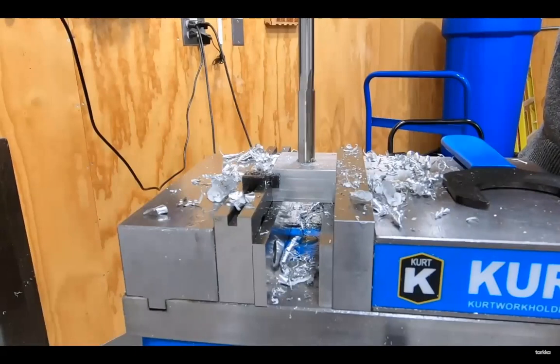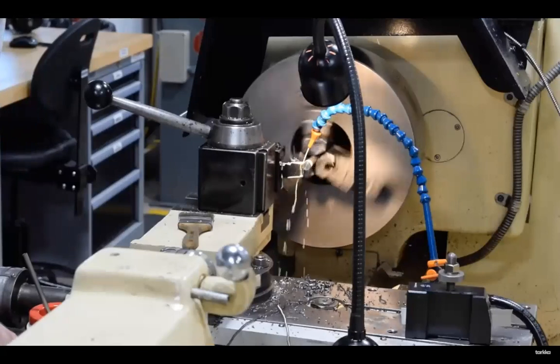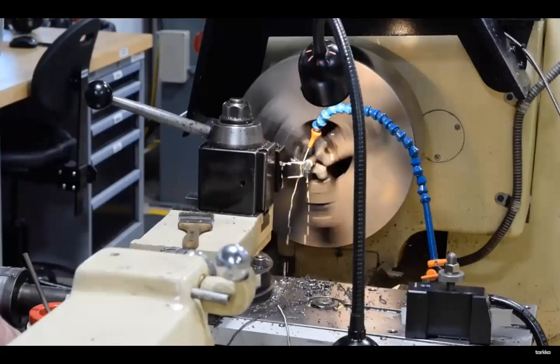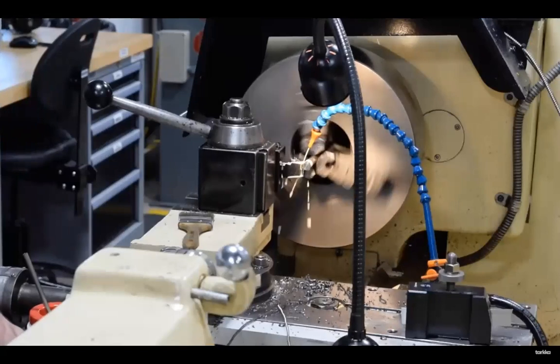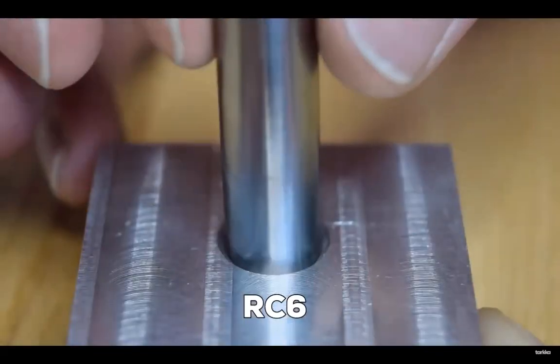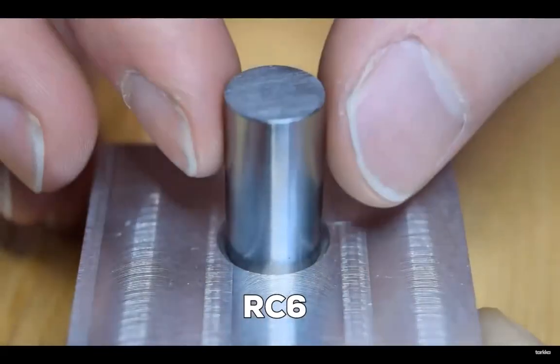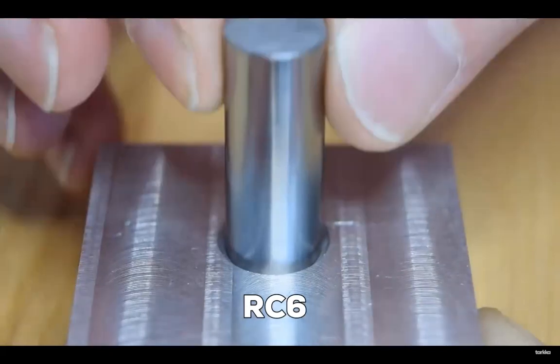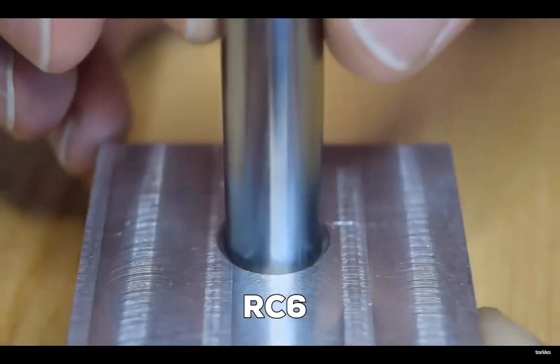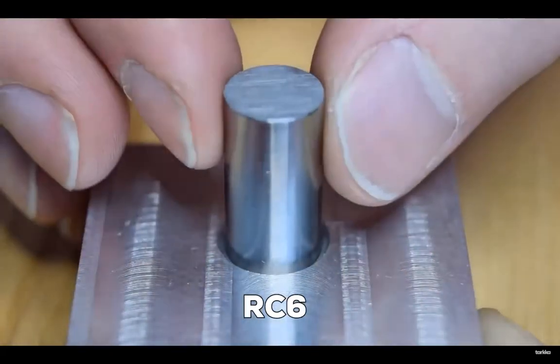We ream this RC6 hole, but you can probably achieve this tolerance on a CNC mill if you compensate for tool diameter in the control. A drill is not likely to hit this tolerance every time. Depending on the size, this is probably about the tightest shaft tolerance that you can expect to hit consistently by turning. This is the fit to use when you need two parts to align to each other, but some clearance is acceptable. This is the tightest fit that can be readily achieved with normal manufacturing processes and without undue effort.